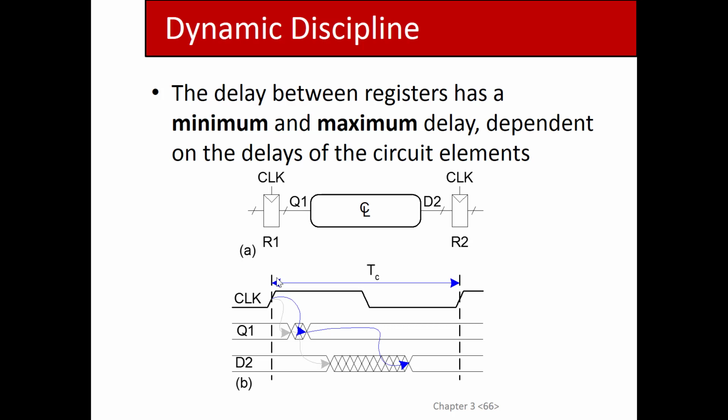We have to do the next amount of work for the next cycle, but we have to hold the inputs. We don't want any inputs arriving at D before I'm ready for them, right? And that's the hold time. So the hold time is a function of contamination delay. Does that make sense? So setup time, think of it this way: setup time is what's going on in this cycle. Hold time is about worrying about what happens next cycle.